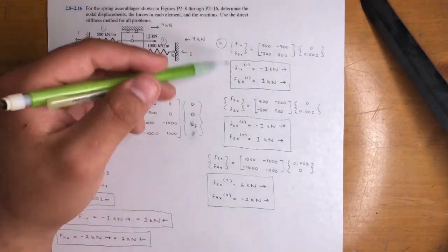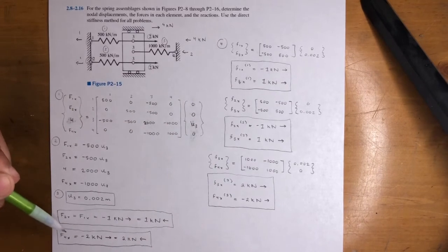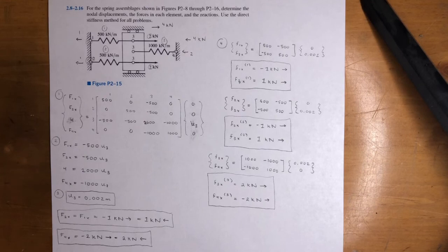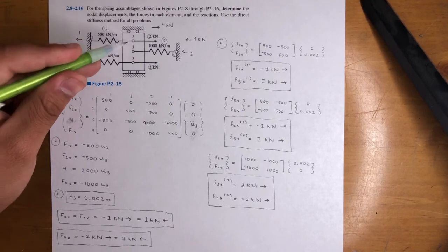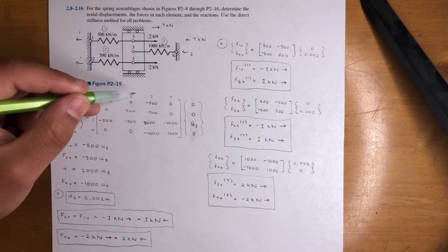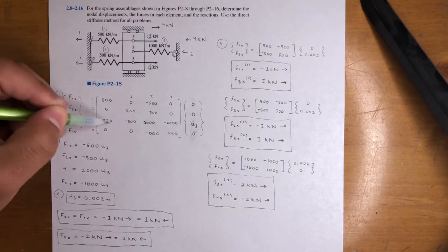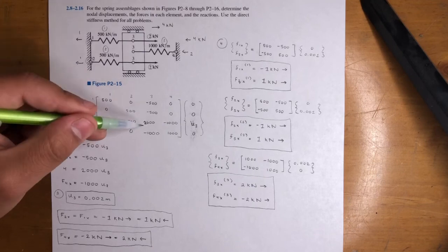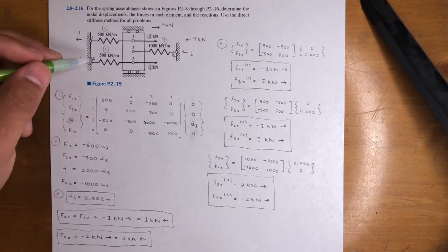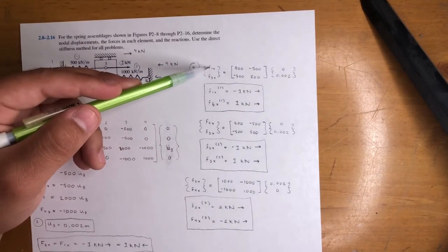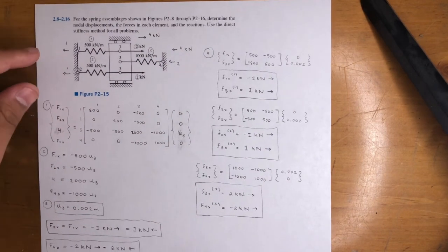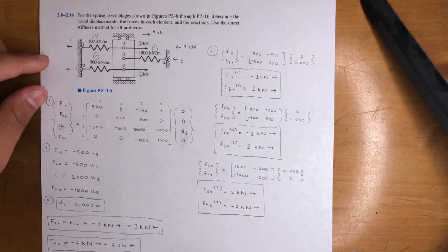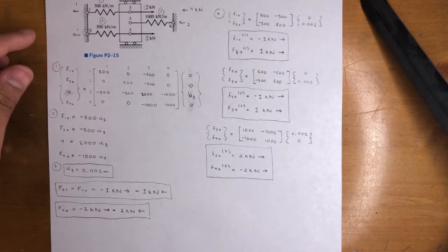All the local elements were verified, the forces were already verified, remember? And I guess the biggest takeaway in this problem is knowing how to set up the global stiffness matrix. Be careful, it's between nodes 1 and 3 in this case, so it's row 1, row 3, and column 1, column 3. And then also here, remember F1x, F3x, because it's between those nodes. But yeah, easier problem, just a little trickier, but there it is.